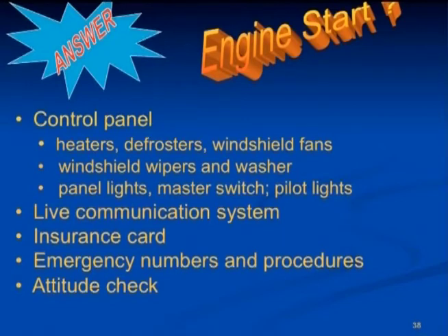For your control panel, again, for most people, this is off to the left. Make sure your heaters, defrosters, and windshield fans all work. Make sure that your windshield wipers and washer work. Check your panel lights, your master switch, and the pilot lights. Make sure your live communication system is working. Make sure you have your insurance card, emergency numbers, and procedures in place.